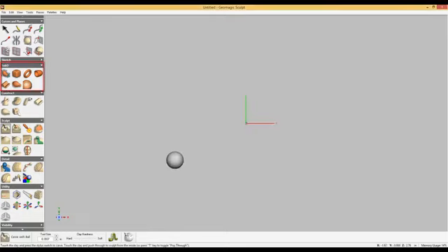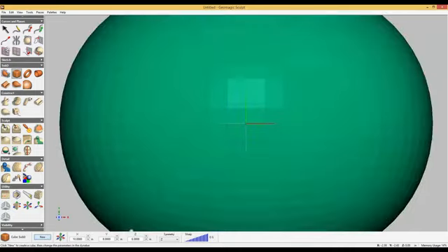On the sub-D palette, click the Cube sub-D tool. In the Dynabar, change the X, Y, and Z shape dimensions to 10, 8, and 6, respectively. Set the symmetry to the Z-axis. This will mirror any changes from one side to the other. Click the New button. The new sub-D shape appears.